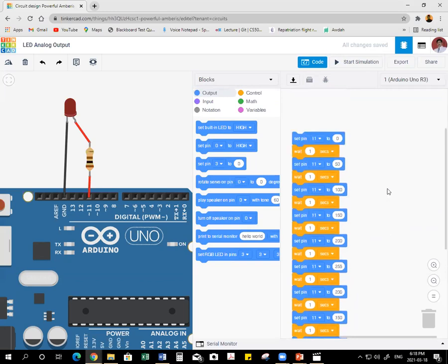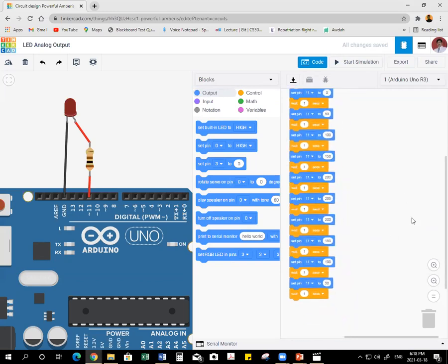Okay, see the blocks, I will minimize it. So what I'm doing here, to the pin 11, all the same pin 11, we are giving output in the 0 to 255 range. Every time I'm adding 50. So from 0, 50, 100, 150, 200, 250. But the maximum value I gave is 255, and decreasing down means minus 50: 255, 200, 150, 100, and 50. By default, if you rotate, it will come to 0 here, because it is a continuous loop, an indefinite loop we can say.